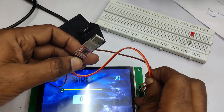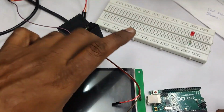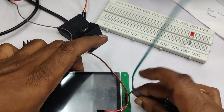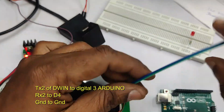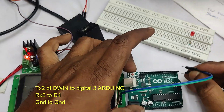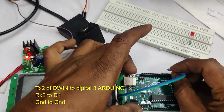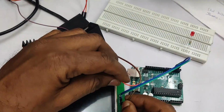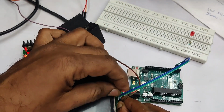Now let us connect the Arduino to the DWIN display. Remove the USB to TTL device and connect RX2 to TX of Arduino, that is the software serial we are using. So TX is digital pin 4, and the TX2 of DWIN goes to digital pin 3 of Arduino.